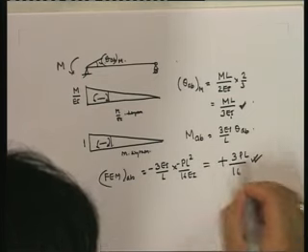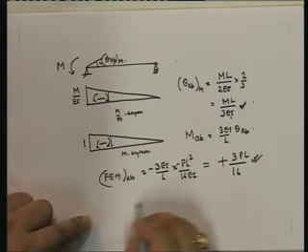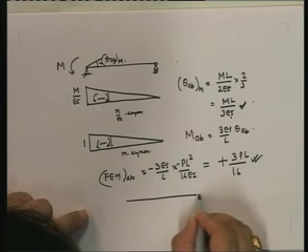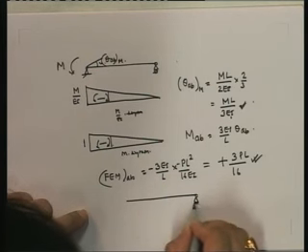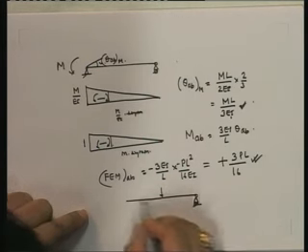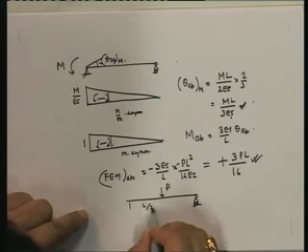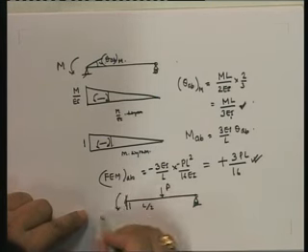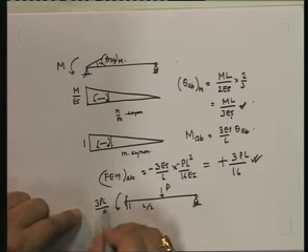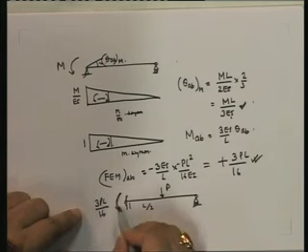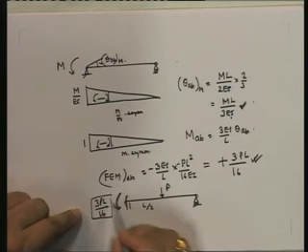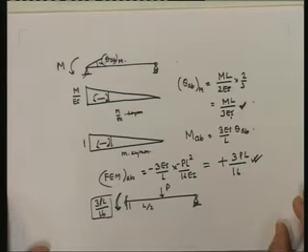Sorry, minus minus plus. What is that then? What is the fixed end moment? For a load applied at L by 2, the fixed end moment over here is positive 3PL by 16, which means anti-clockwise. We've already derived that earlier.